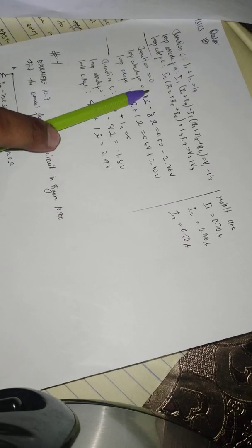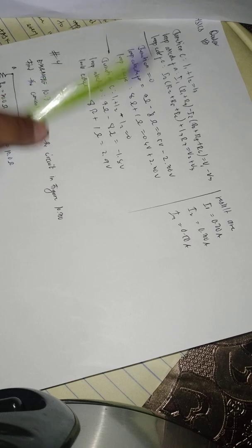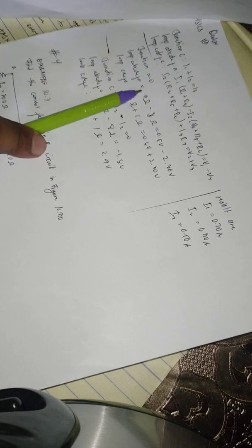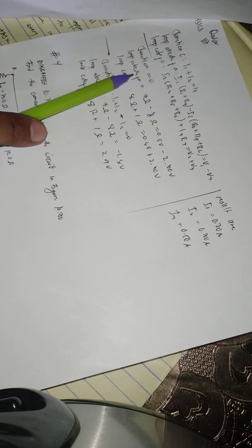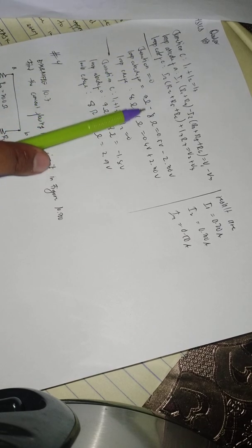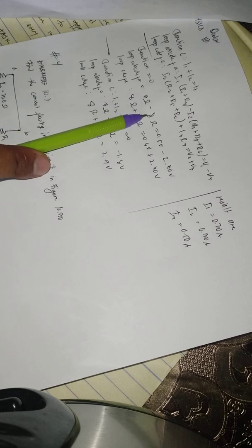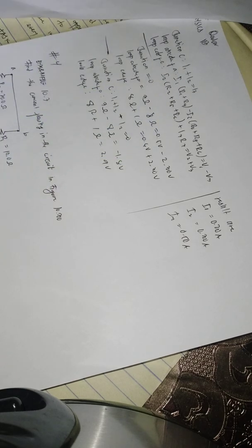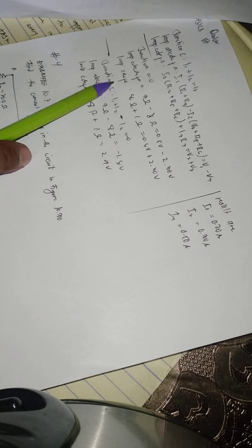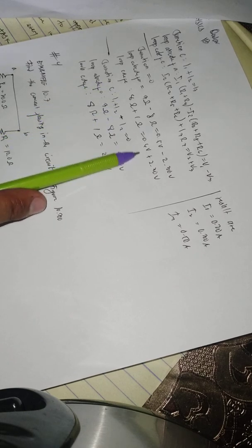For the junction, I sub 1 plus I sub 2 minus I sub 3 is equal to 0. For the loops, 3 ohm I sub 1 minus 8 ohm I sub 3 is equal to 0.5 volts minus 2.30 volts, and for loop CDFC, we have 0.6 volts plus 2.30 volts.